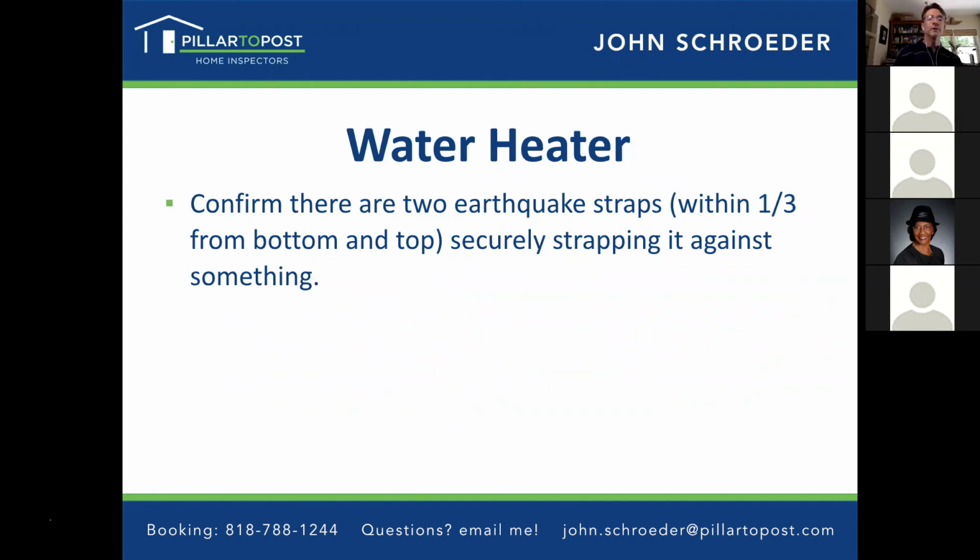With the water heater, you want to confirm that it's properly strapped, which means it's got a strap within 1/3 of the top and 1/3 of the bottom, and it's got to be securely strapped against something. A lot of times you'll see them strapped, but there might be a few inches between the water heater and the wall behind it, which is not really proper. So you want to look for any leaks or corrosion.